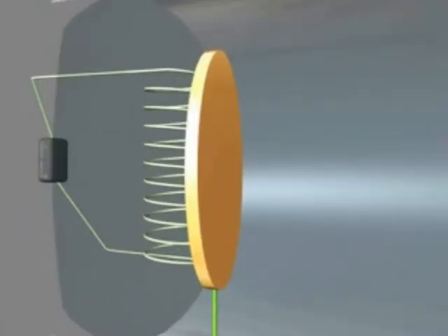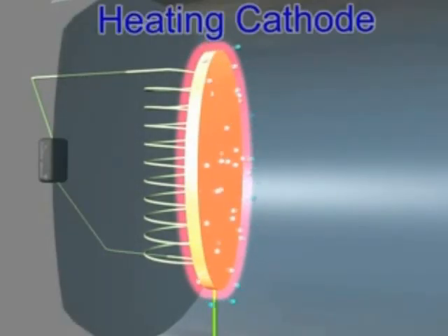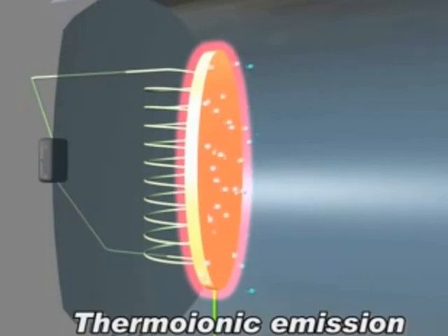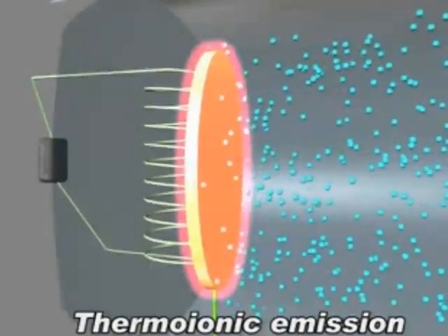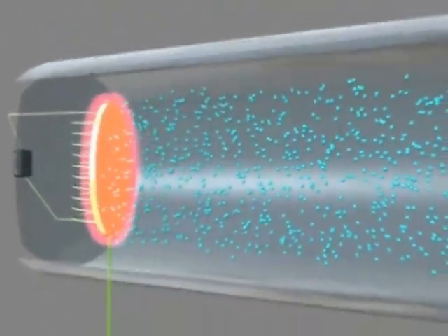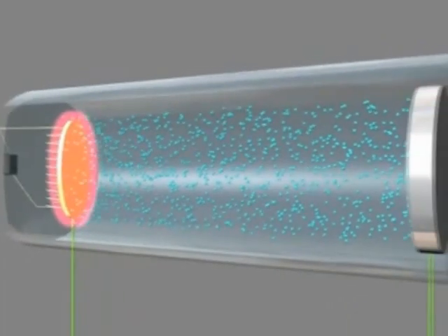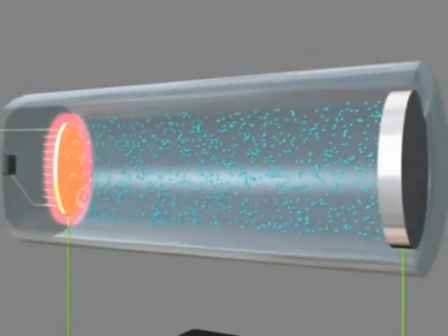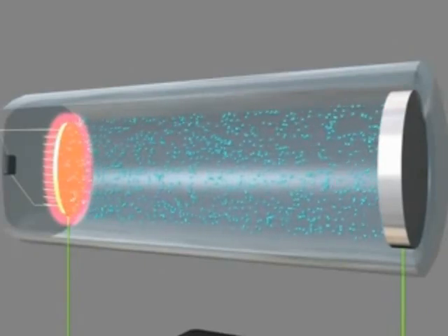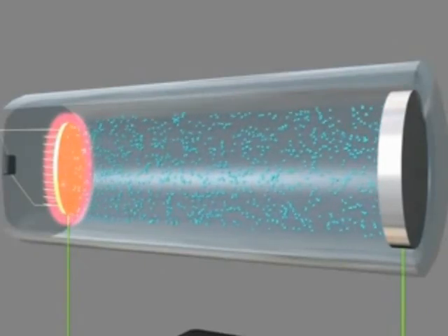If the cathode is heated, electrons of the metal atom are excited and move a little away from the nuclei and then back. So when the DC supply is switched on, the negative electrons are repelled from the negative cathode and attracted to the positive anode, traveling through the vacuum. So we get a beam of electrons traveling through the vacuum. The high voltage drives a current through the heater filament, which in turn heats the cathode to release the electrons.